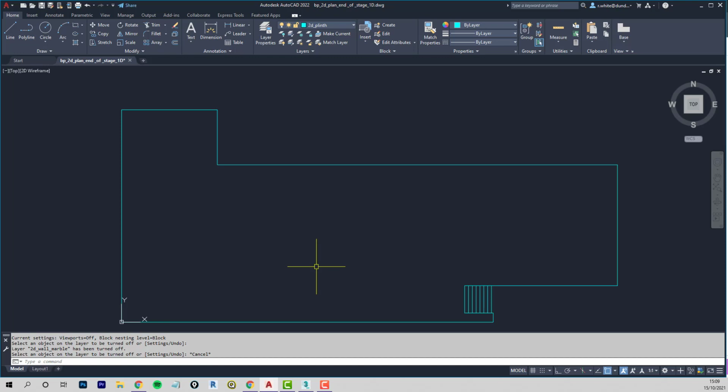So we're going to have a look at drawing the columns and the grid, but I just want to quickly go through what the stages of drawing would look like from here on. At the end of 1B you've drawn the plinth and the steps. 1C is to draw walls using the edges to help you start the walls off, and then different offsets and extensions to get the ends of these walls.